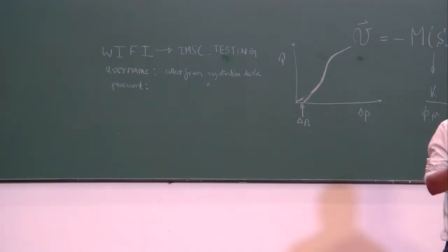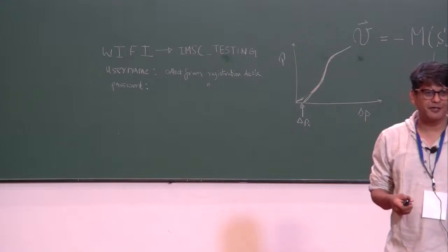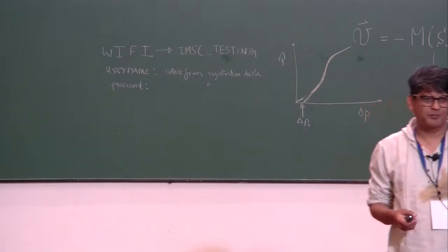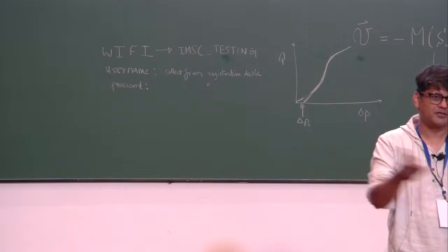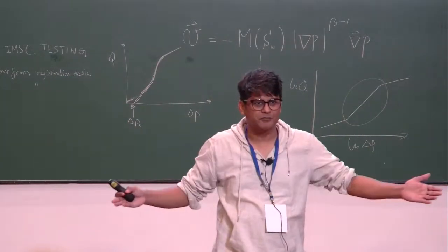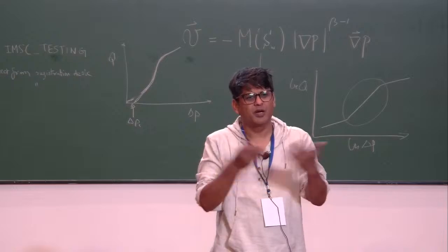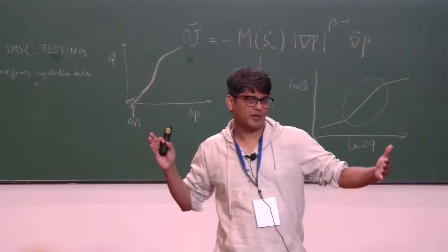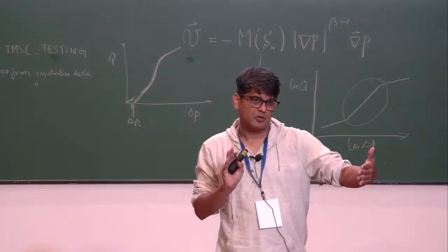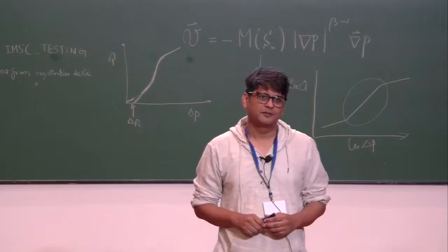You're saying rightly, that because you have a time dependent forcing term in my system, my Euler buckling equation doesn't give me just one particular solution. It has a combination of all kinds of modes in my system. So why do I get one? Loading stops and then it starts to push. So what I fail to take away is that instead of it being buckling, maybe there is an inertia effect involved of the individual masses, and hence it is elastodynamic or wave mediated. In what way am I incorrect here?